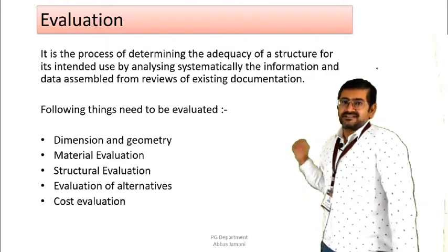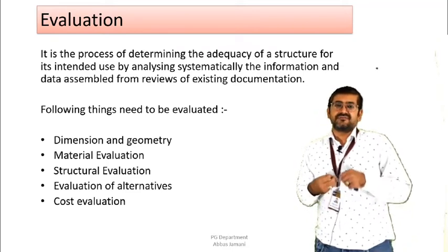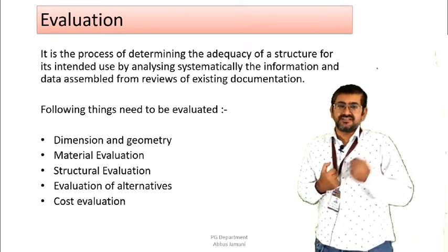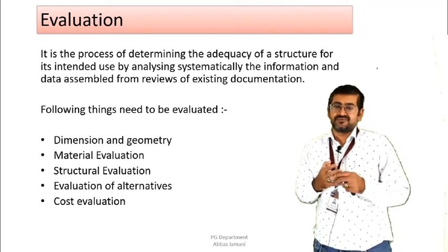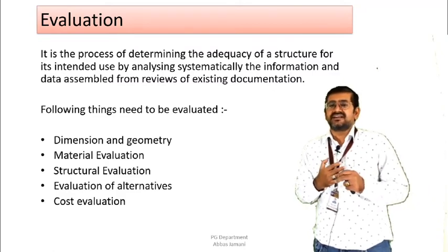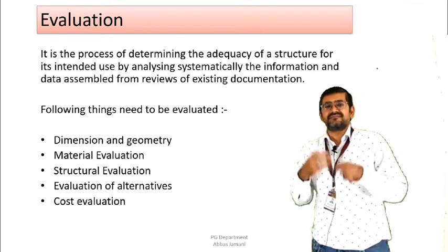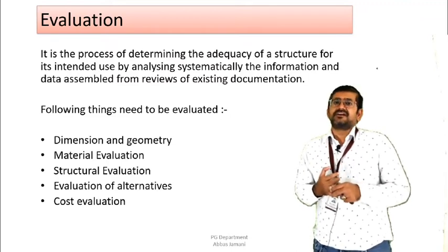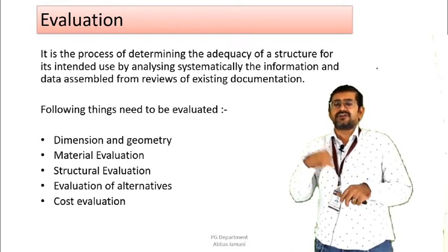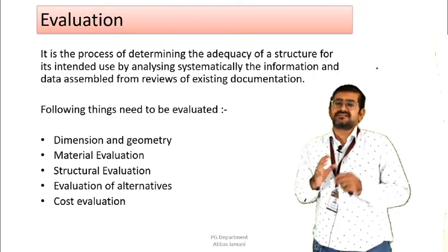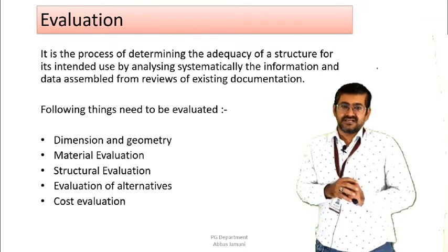Right? Then structural evaluation. In case of structural evaluation, you will need to check whether the structure is capable of undergoing this change or not. This evaluation can be done in three forms. First, you do only an analysis model, that is, for example, you carry out the analysis using FEM or some other kind of model. Second, you also prepare a physical model. And thirdly, you check with respect to the provisions of the current code. Now, after doing all these three evaluations, you will be able to decide whether this structure is capable of undergoing these necessary changes or not, right? So that is why the structural evaluation part is there.